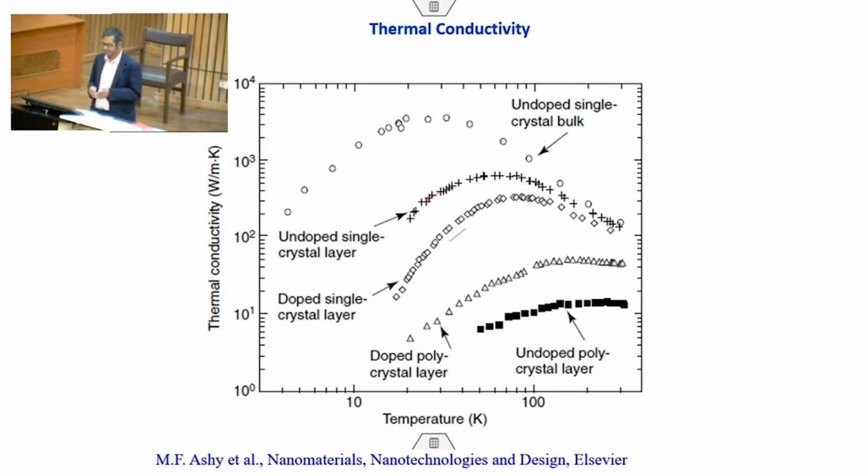So, the problem is it is not theoretically understood how to treat these nanoscale pores for thermal transport. Okay, it is not clear, but nonetheless the pores are not good for thermal transport, that is very clear to understand. Okay. So, hence as you can see here, for the 2D nanomaterials, the effect of the dimension is very distinct and clear on the thermal conductivity,